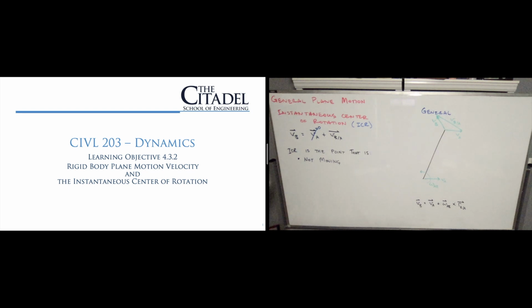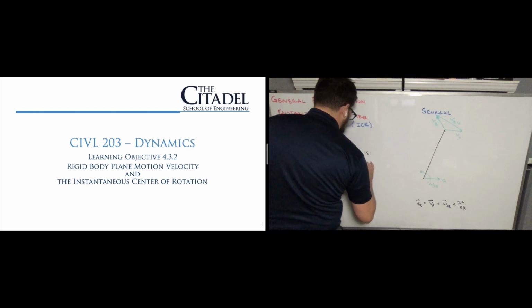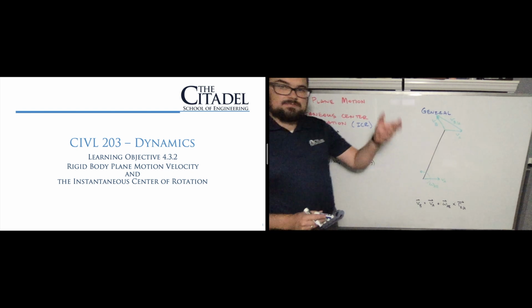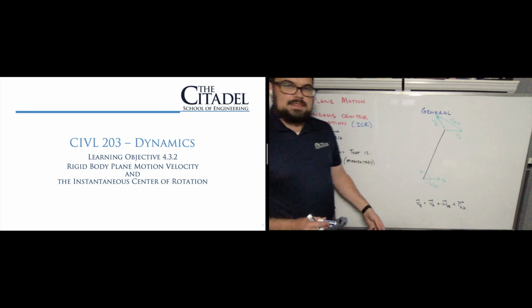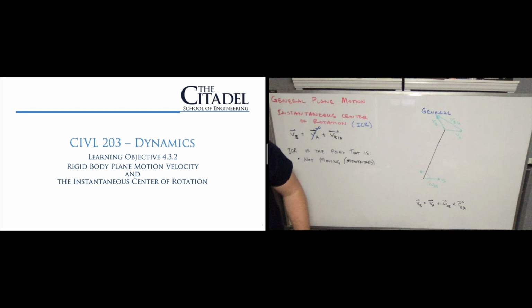And this may be a momentary not moving, where much like we say that the ball at the top of its flight has come to a stop, the ICR has only temporarily come to a velocity of 0, and the body appears to rotate about it.